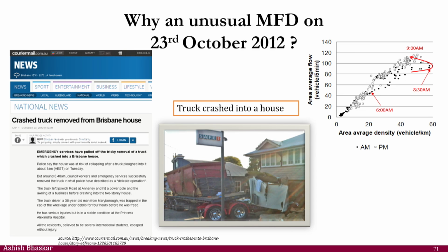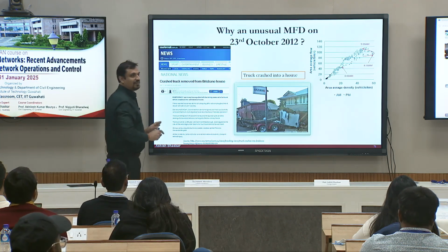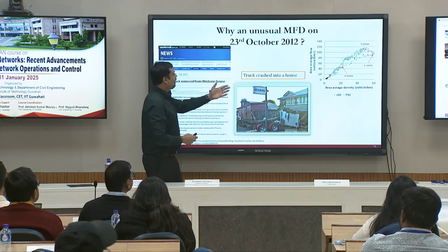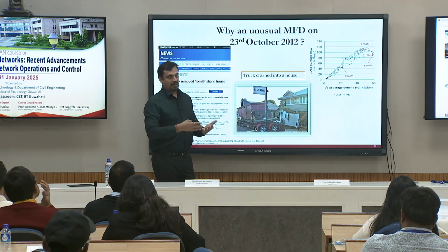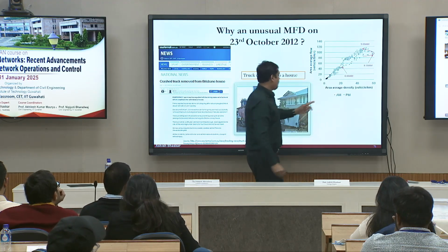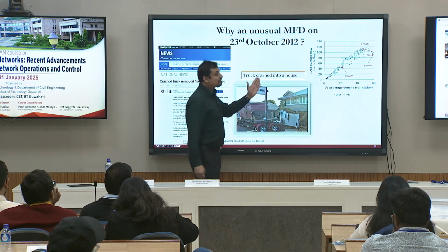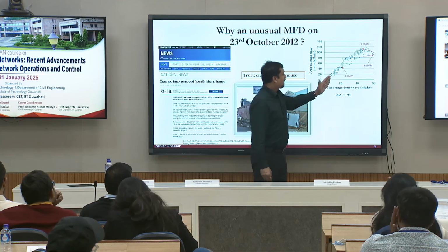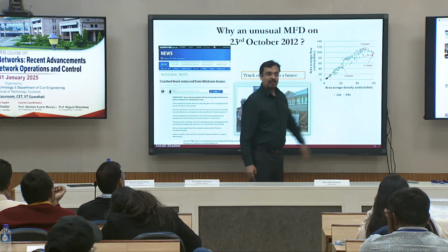The one I was saying, that when you draw the fundamental diagram for one section, you have one shape. You can accumulate sections, you will have another shape. They may not be the same, but the functional form is still the same, and this is well verified from that angle. Even any fundamental diagram will have its own disturbance, right? Here, an accident happened, capacity has gone from bad to worse, so your speed has significantly dropped, and then it is moving in that manner.